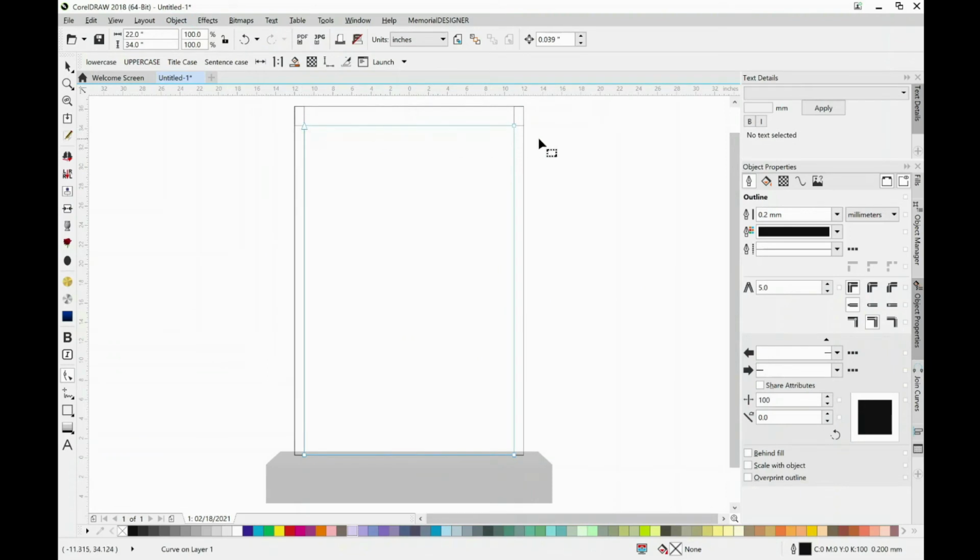And you'll see that those have gone from black dots to normal points, etc. And these lines are now just straight lines, and I can move an individual point out. But what I can't do is move and create a curve. These are still all lines. So if I just go undo and undo. What I want to do is select all of the lines and then right click and say make those curves. So these lines are now curves. So when I pick the line up, you'll see it now creates a curve rather than dragging all the boxes.